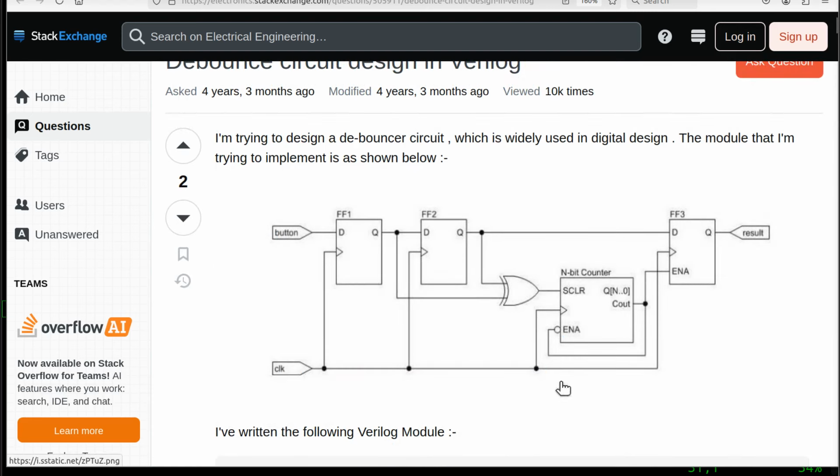This one is an interesting implementation of a debouncing circuit. We're replacing this, okay? But here's the synchronizer. You got the switch coming in, the same clock, collects them both. There's your shift register. They did something interesting here, looking for edges. This approach did not work for this person, so that's what we're throwing out. But basically, you've got this shift register followed by go somewhere and process something.